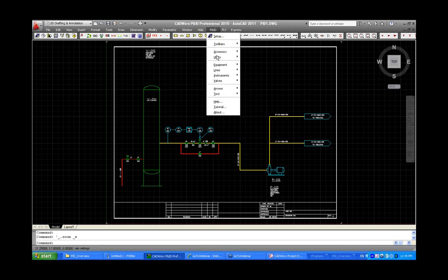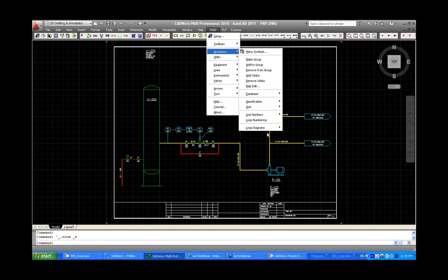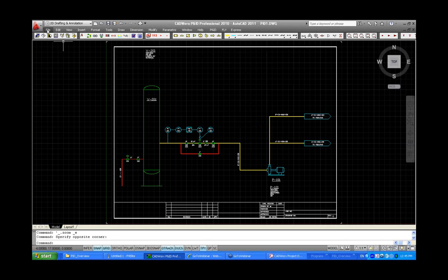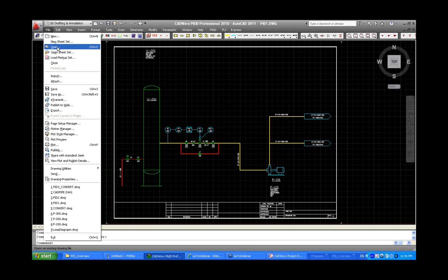Okay, so now the first thing we want to do if we wanted to create a loop diagram is we need to go in and create a table. And the second thing we do after the table has been created is we generate loops. So to create a table, you basically have to create an AutoCAD drawing that has fields in the brackets, and the fields that are in brackets is actually the text that the database recognizes and allows the use of the database tables for us to update information and push information on the actual loop diagram itself.